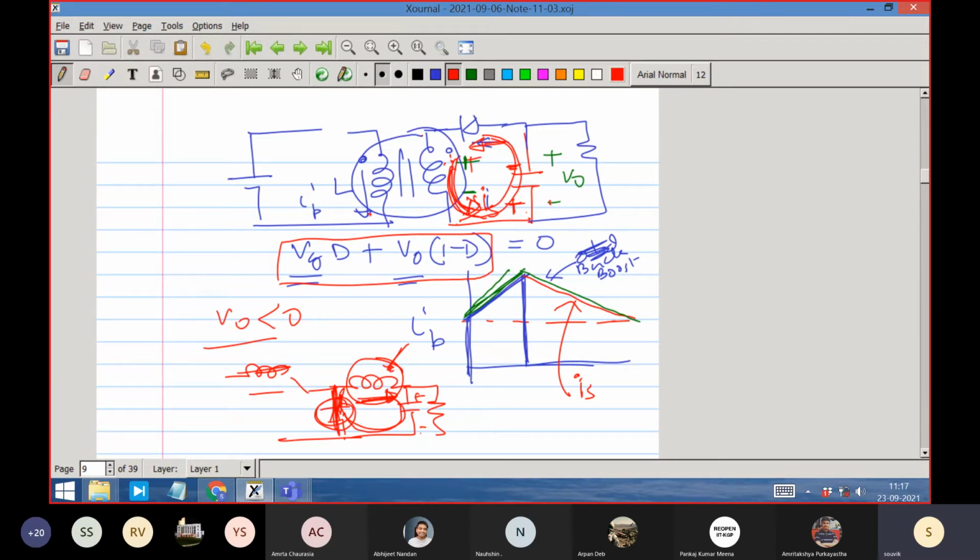If you place the diode wrongly, the diode will blow, simply because this inductor will try to develop as much voltage as is necessary to continue the path. So the diode will eventually be ruptured to make sure that the energy gets a path, right? If you put the diode wrongly, it will develop a very high voltage across it. But here, it needs to develop only slightly higher voltage, V0 plus diode drop. That much voltage it needs to develop. The moment it develops that voltage, it gets a path and it is happy. It will not do anything extra.